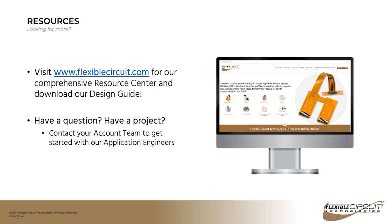Yeah, that's a great question. I kind of touched on that a little bit during the presentation. Crosshatch shields are used on a regular basis for high-speed signals, and it gives you two benefits. The first benefit is that you're removing some of the copper in that plane, which is going to make it more flexible. The second thing is that by removing the total surface area that is broadside coupled to that plane, you are reducing the capacitance, and therefore you can actually make your space in between those layers less.